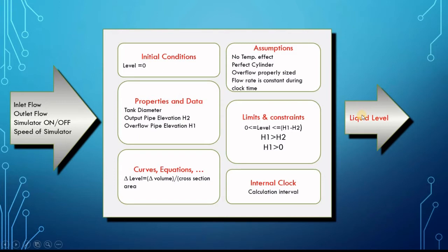Now, if you have a pump in series with another pump, what about the second pump? You have to think about what I will get from this simulator. Maybe it's completely different from the first pump. The first pump's inlet comes from a tank. The second pump in series would have the flow rate coming from the first pump. So you have to think about what your output is.